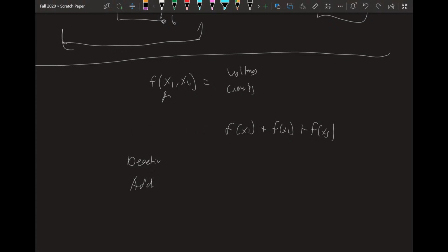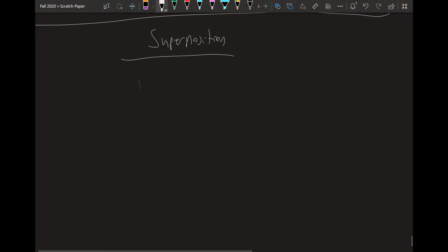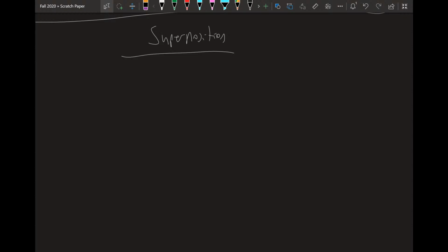All right. I'll actually just do that then, and if we have time at the end, then we can go back and do some more problems. So, superposition. Let me more formally introduce it. And by that I mean you read my notes. So for any of you in signals and systems, this should be something you know. Our circuits are LTI, linear time invariant systems. And so superposition is just a property of these LTI systems, which means that essentially the output of the system with all inputs applied at once is the same as each input applied separately and then added up. So like I said before, if our circuit is a function which has inputs as sources, we can look at the circuit with just one or more of these inputs active, and then add them all up to get what would have resulted if we had solved the circuit with everything active at once.